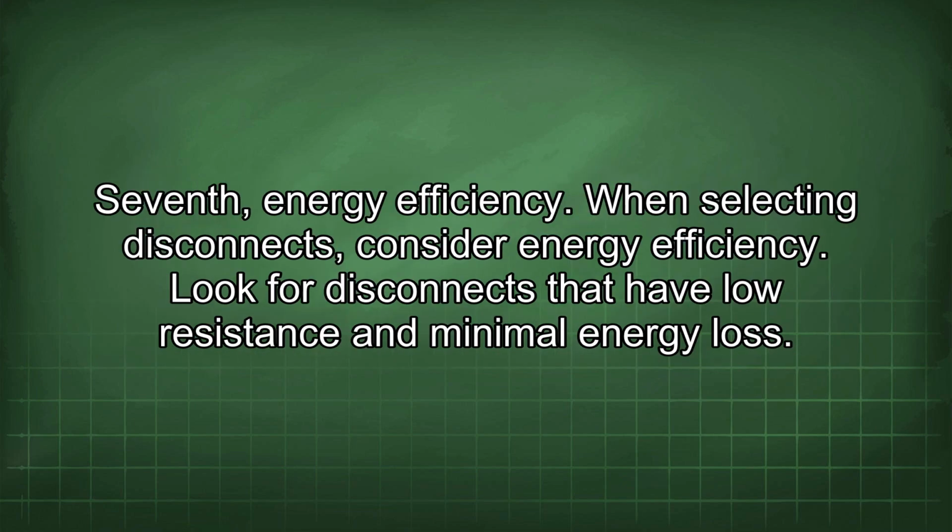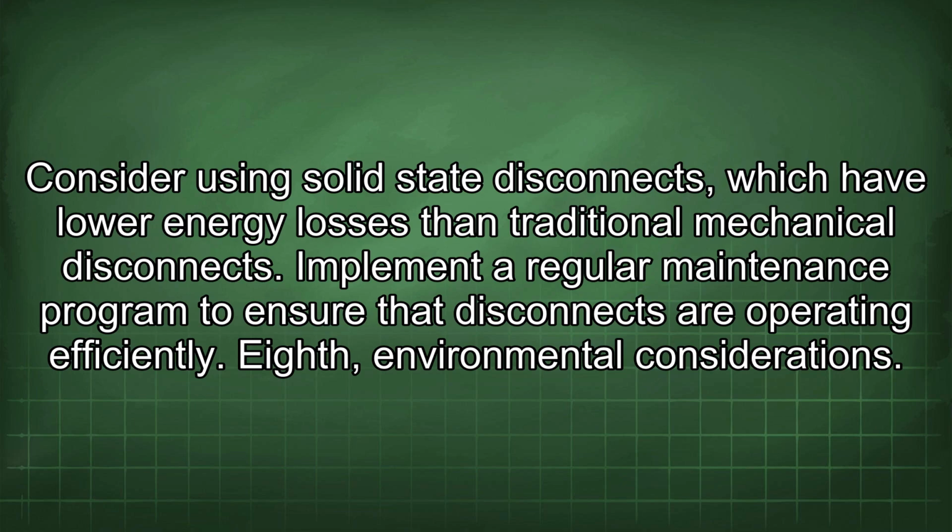Seventh, energy efficiency. When selecting disconnects, consider energy efficiency. Look for disconnects that have lower resistance and minimal energy loss. Consider using solid-state disconnects, which have lower energy losses than traditional mechanical disconnects. Implement a regular maintenance program to ensure that disconnects are operating efficiently.